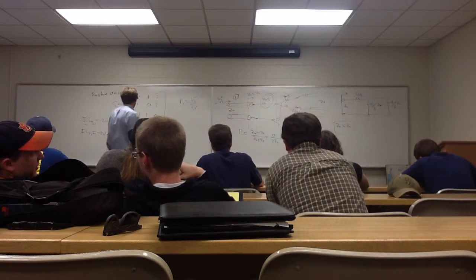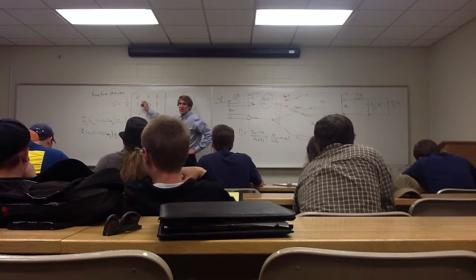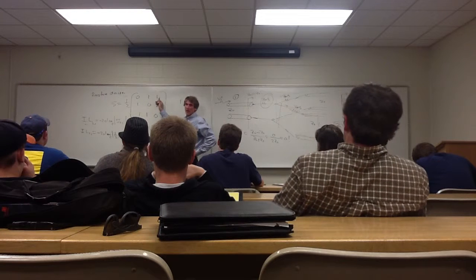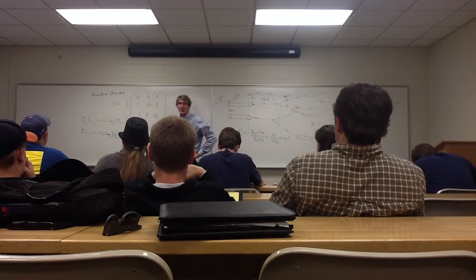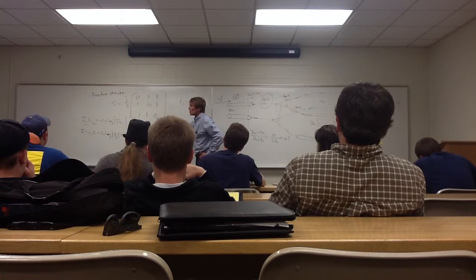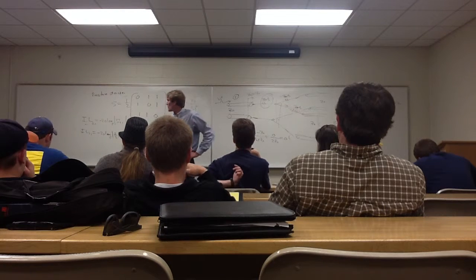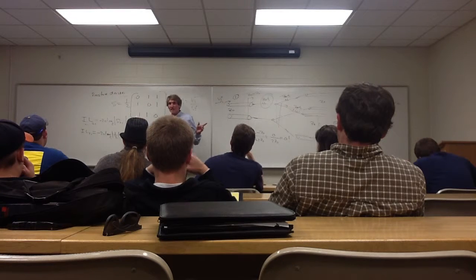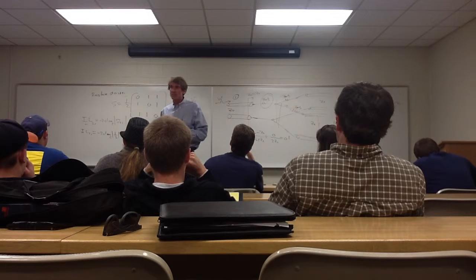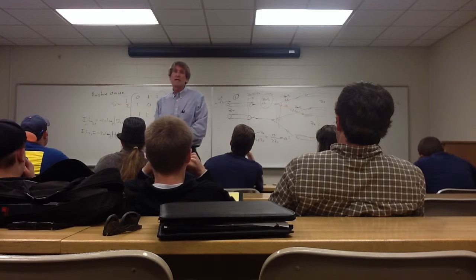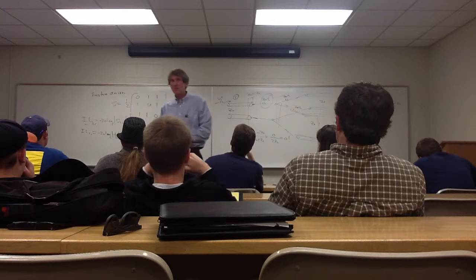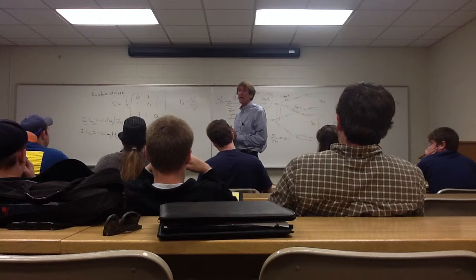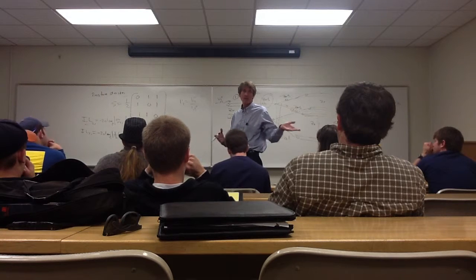Now on this one, for the S parameter matrix, you see the insertion loss terms that would be for 2-1, for 1-2, for 3-1, and so forth, all the way down here, or for 1-3, I'm sorry. If you look at all these values, they would be a value of a half, wouldn't they? Do you all agree? It's 1/2 times this. That means we have 6 dB of attenuation. That's a lot. We're paying for this divider, even though it's very low in terms of the expense, but we're paying for it in power. We're losing a lot of power, a lot of signal strength.